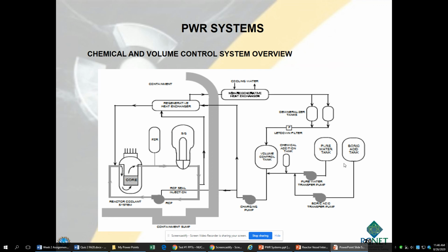And that's just a very fine control. The other way is, of course, these control rods. So I have two different ways to control power, and one of them is this CVCS, Chemical and Volume Control System. I also have two demineralizers over here. So, right, it's controlling the chemicals, it's controlling the volume. So it's cleaning up that water that's coming through and just making sure that I don't accidentally corrode my fuel.